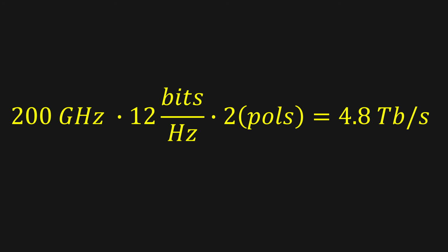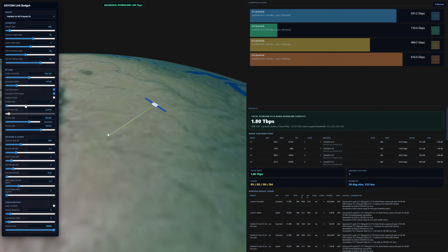So even if we could hypothetically use 200 gigahertz of bandwidth over the entire microwave spectrum, our data rate still caps out at around 4.8 terabits for a single link between 2 locations. The obvious solution is to simply connect your satellite to many different ground stations, multiplying your data rate with more parallel lanes. However, we do have another option that could give us unimaginable serialized throughput, and that will be the topic of today's video: laser links between the Earth and space.